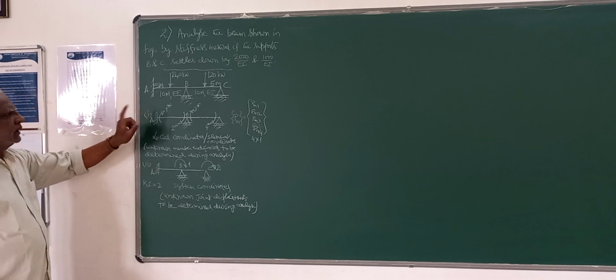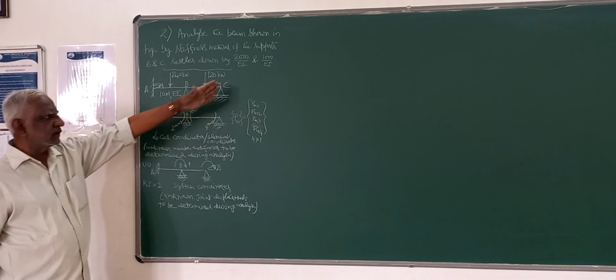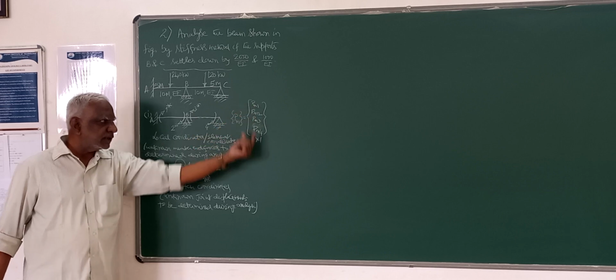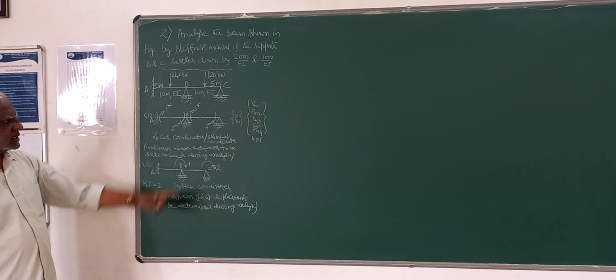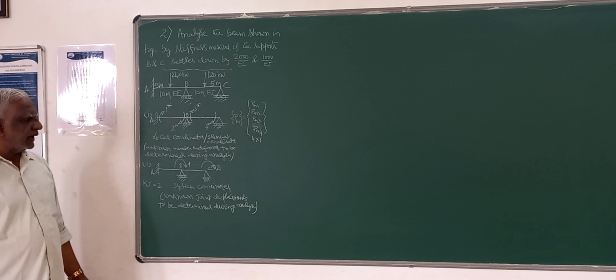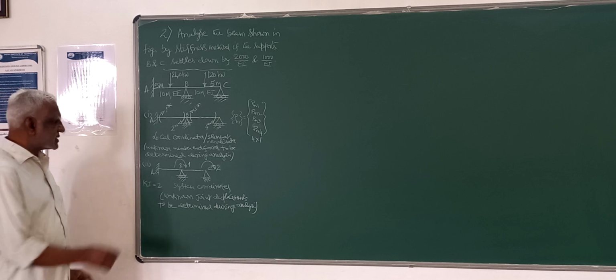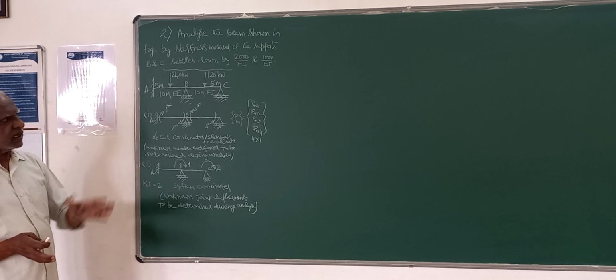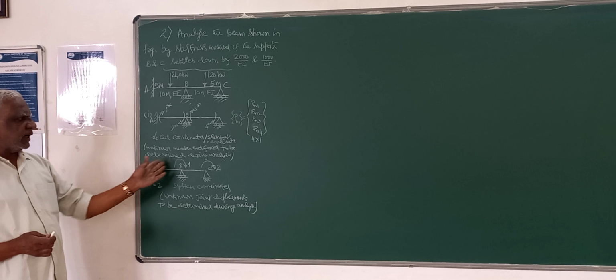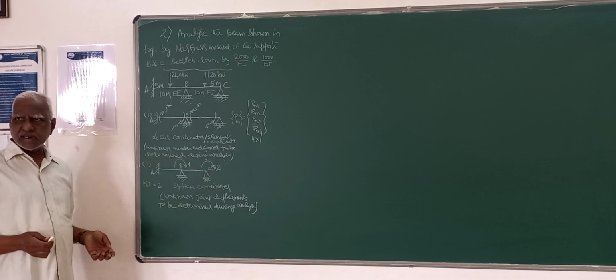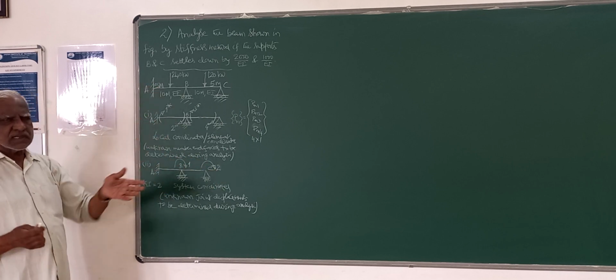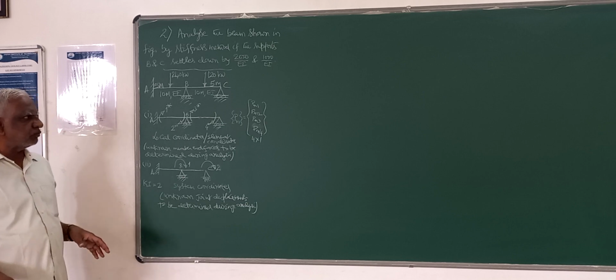So first step, element coordinates, that is the unknown member end forces that you have to determine during analysis, indicated by that matrix PM. And in the second step, unknown displacements, because analysis means evaluation of the unknown displacements as well as the unknown internal member forces.